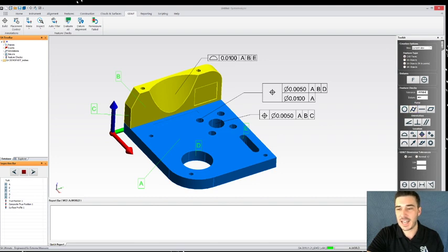So when I select, I'm also going to preset my GD&T dimension tolerances to set them to nominal, and I'm going to auto set the nominal diameter, and I'm going to go low, let's see, whatever the tolerance on this hole would be. We'll do plus or minus 2, minus 0.002, and high 0.002. And that will set my diameter tolerance on this when I select the true position.